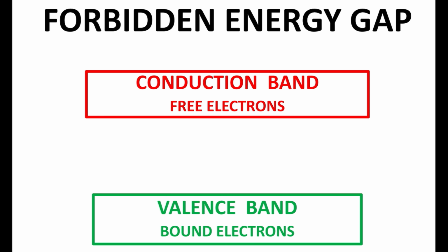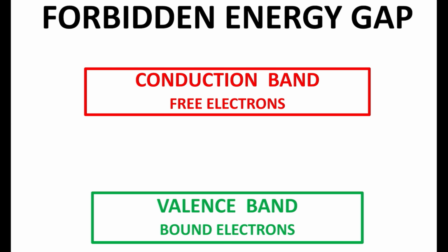The valence band electrons which have no role in chemical bonding are called free electrons, and the energy levels of these free electrons are higher than the energy levels of bound electrons. The energy band of these free electrons in a material is called conduction band of the material, because conduction of electric current in a material takes place due to movement of these free electrons.